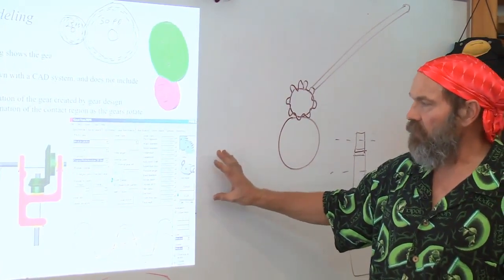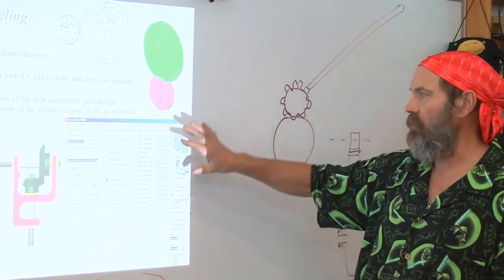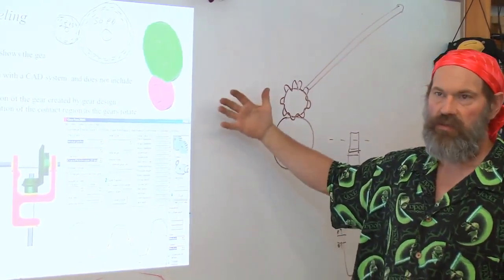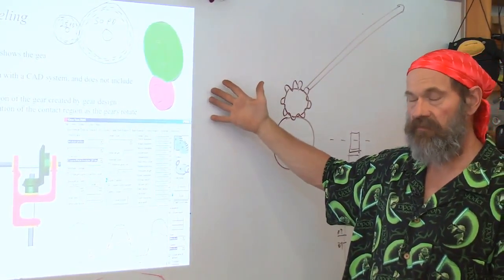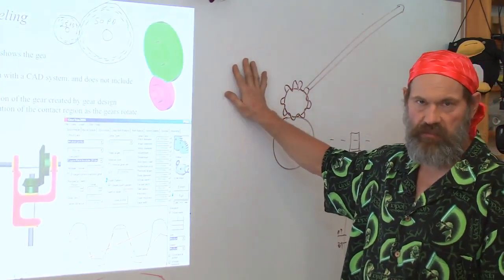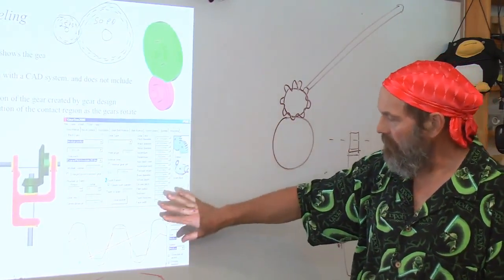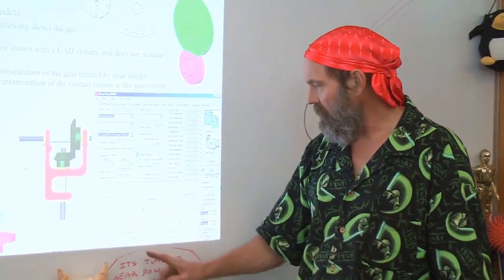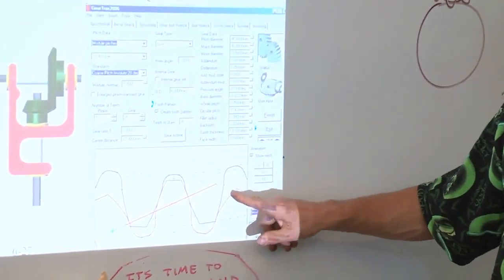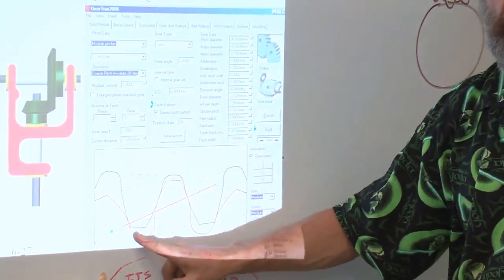What you look for in a gear design program is that you start with inputs in terms of the size of your gear teeth that came from what you calculated you want to have to resist the loads, and you got that from one of your gear design spreadsheets, for example, that come with the course. The picture that the CAD tool will give you will help you to determine what the undercut is that's happening on the teeth. So does it look like you have good conjugate action?